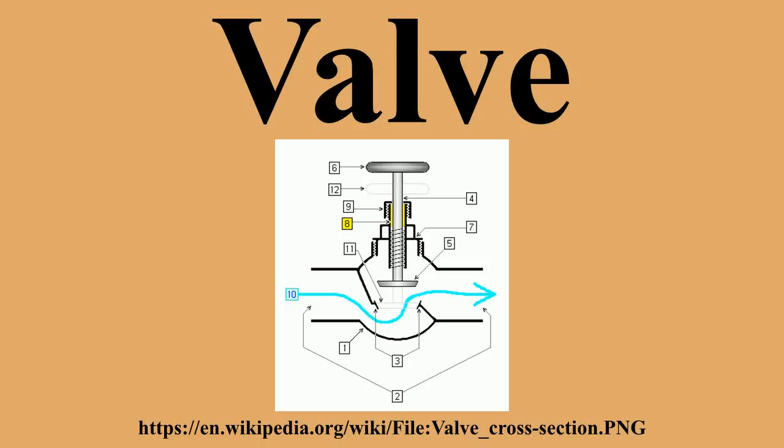Four-port valves. A four-port valve is a valve whose body has four ports equally spaced round the body, and the disc has two passages to connect adjacent ports. It is operated with two positions. It can be used to isolate and to simultaneously bypass a sampling cylinder installed on a pressurized water line. It is useful to take a fluid sample without affecting the pressure of a hydraulic system and to avoid degassing.